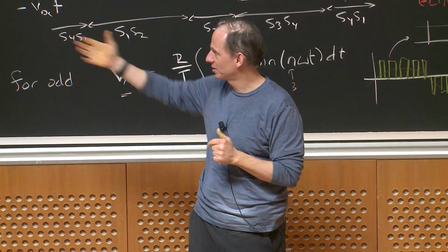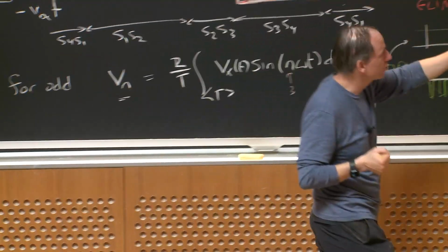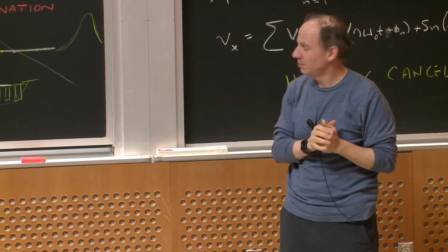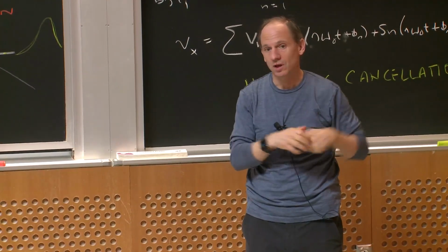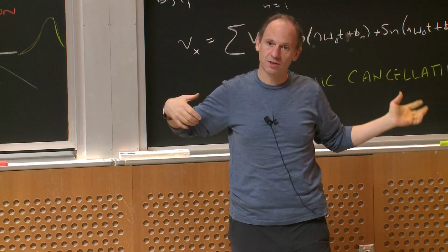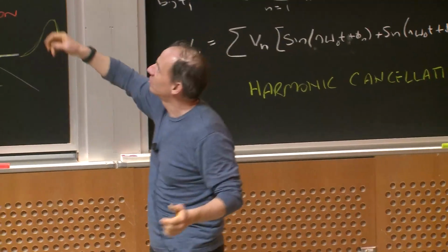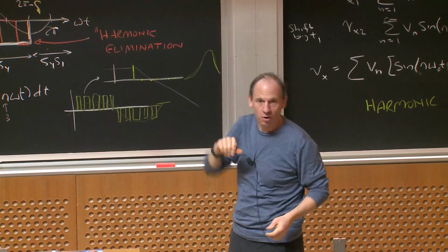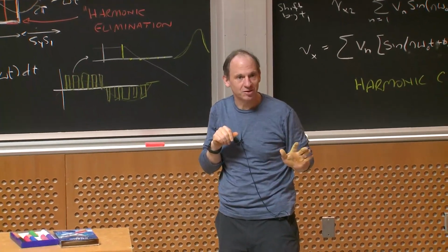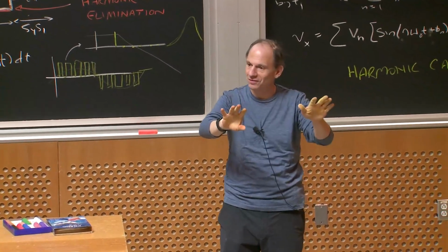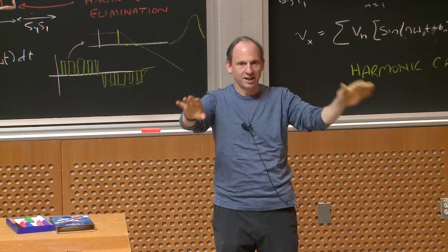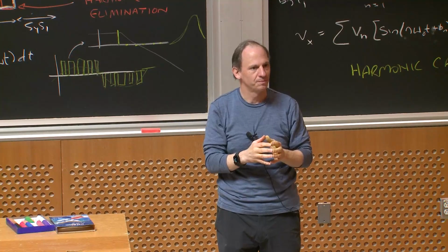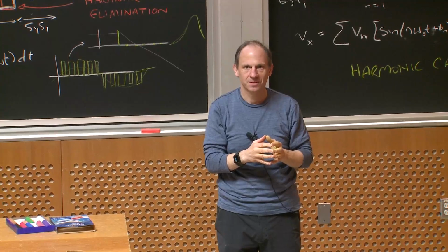It's widely used in DC-DC converters. It's also used to kill off unwanted harmonics in inverters. Harmonic elimination is also used, and there's nothing that says you couldn't do the two together. You sort of saw that, right? Instead of using just one pulse per half cycle, I could use some pulses per half cycle to eliminate some harmonics, use some phase shift and eliminate some more, and I can intermix those two, and they get very nicely, easily filtered waveforms. Any questions about that?